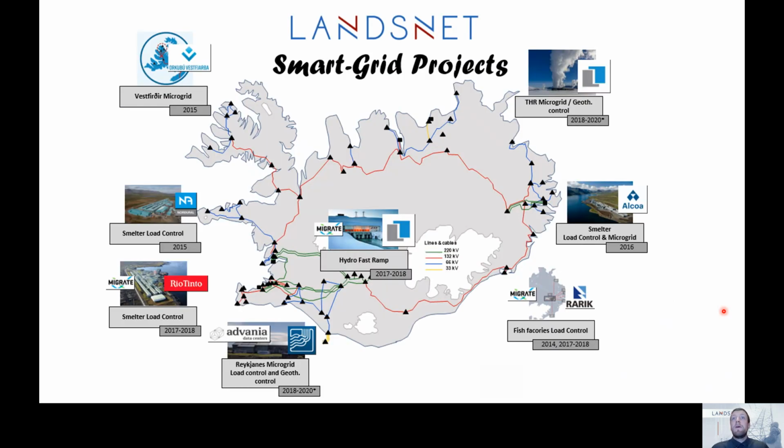Coming to the response providers themselves, this is an overview of what we are using within the scope of these wide area protection projects, and it mainly focuses on big load consumers, the smelters. We have 3 big smelters in Iceland, and all of them have implemented some kind of load control where we can send them signals to use the load as regulating power. So we can ask them to both increase and decrease the load in a very quick manner.